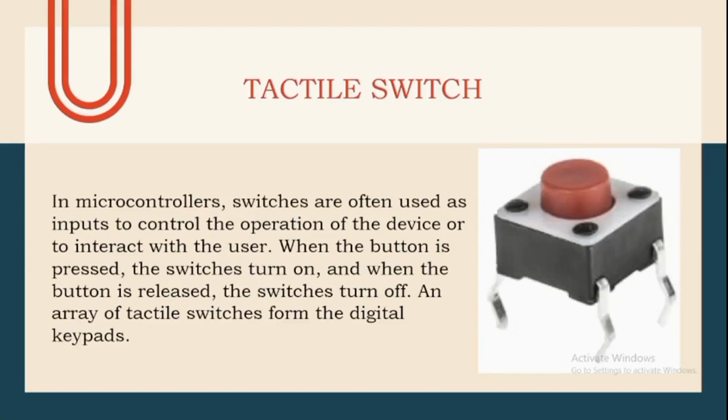Tactile switch. Tactile switches act like buttons. We use them as user input, such as selecting modes, starting, pausing, or stopping the washing. For instance, if you press one switch, it might trigger quick wash and another for rinse. The microcontroller detects the logic level from the pressed switch and responds accordingly.